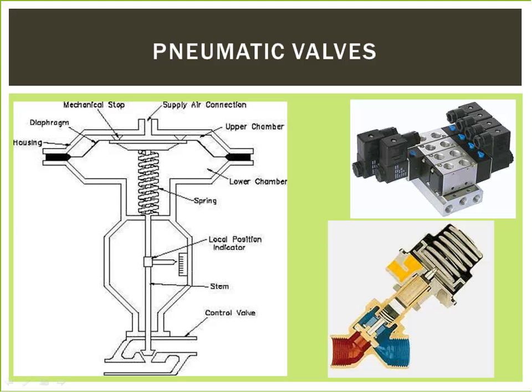A four-way directional valve has four distinct ports, two of which connect to actuators, one that connects to a pressurized airflow, and one that serves as an exhaust pathway. They are among the most common types of valves found in pneumatic systems because the four distinct paths allow the valve to effectively reverse the motion of a motor or basic cylinder.